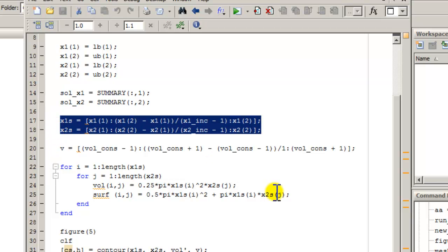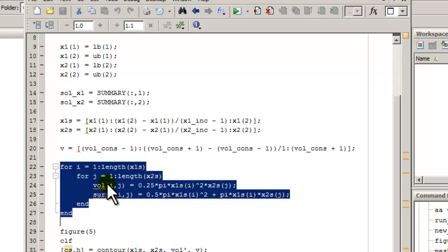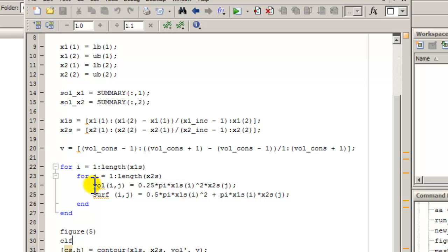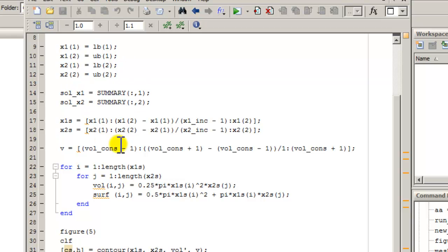these constraints here. You send these constraints to it, and after we define the ranges, we calculate the volume and the surface area. What we're going to do is overlay the contour plots of the volume and the surface area and use all the data from the optimization run to see what the optimizer was doing. We're only going to keep the volume level for the 1000 cc problem, or the 500 cc, whichever.